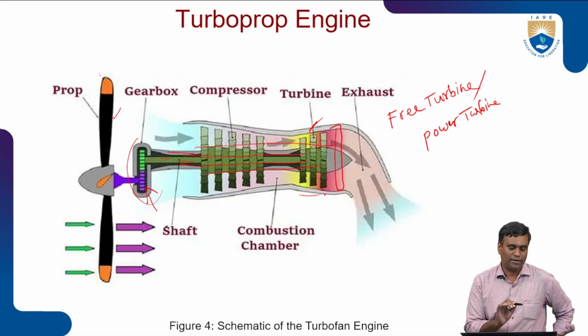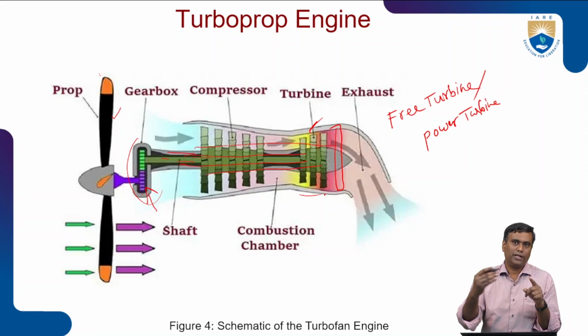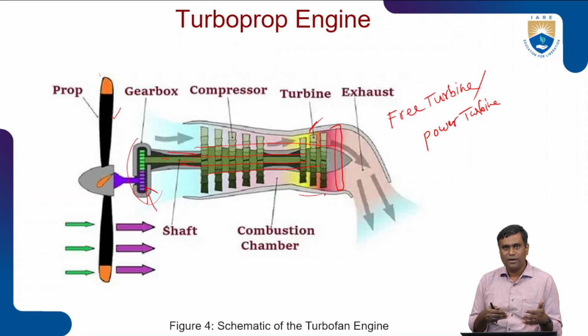That's how we can find out after going to the engine practically, physically. If you rotate the propeller, and the compressor blades are immediately rotating, that is a direct connection, direct to power. Otherwise, in a second possible case, the second type using a free turbine, if you rotate the propellers, the compressor blades won't move immediately.